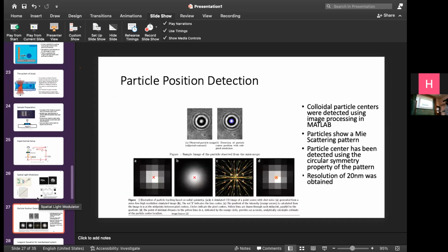And for the particle, we are using image processing again to detect it. We actually did subpixel detection of that particle. Usually you would expect that if I have an image of, let's say, 100 by 100 size, then the particle measurement would be limited to what pixel it is on the x-axis and on the y-axis, let's say 50 cross 50. But we can actually detect a Gaussian shape on top of this particle.